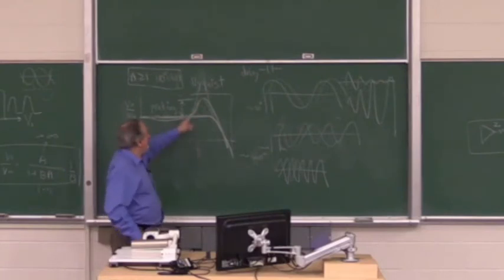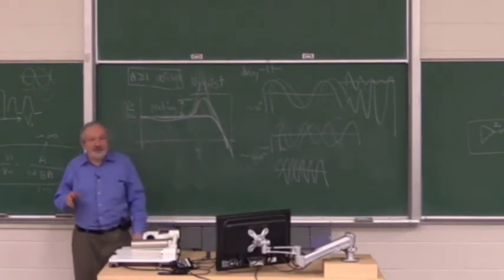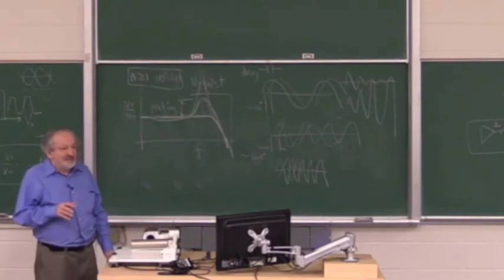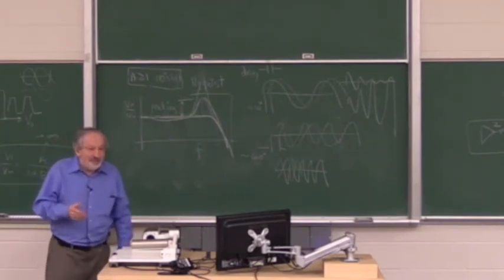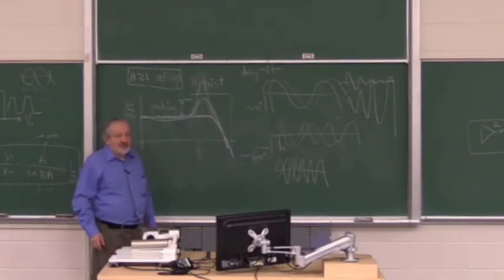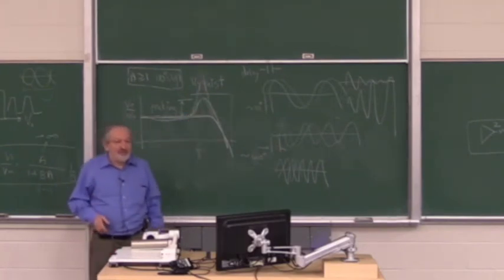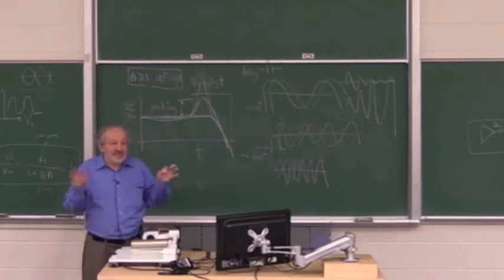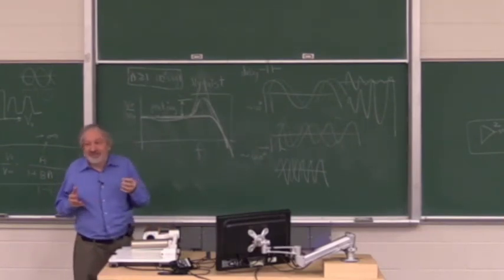Okay, so you can estimate from this how close you are to trouble. You can do this with an op-amp by simply sweeping the frequency, looking at the op-amp output. You can do that with a robot, you can do that with a kiln, you can do that with a whole industrial plant, which is controlled by feedback. So this principle is universal.